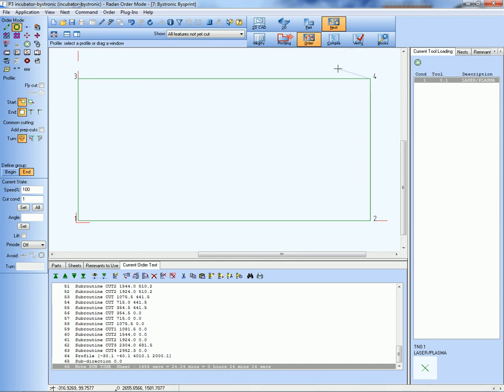So very quickly, from receiving a 3D model, you can check whether you can produce the part, so you know whether you've got the right press brake tooling to do that. You can also check the implications of your press brake tooling on the actual sizes of the parts, so you're going to create blanks that are the right size for the job. And now you have your NC code ready to go.